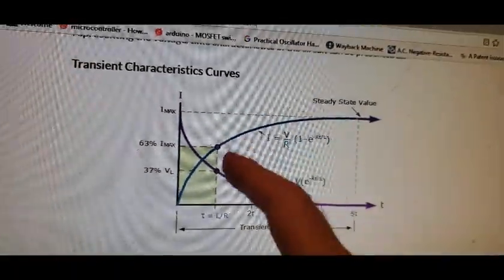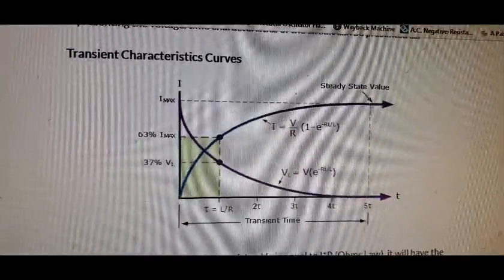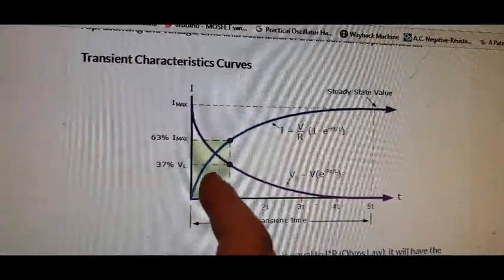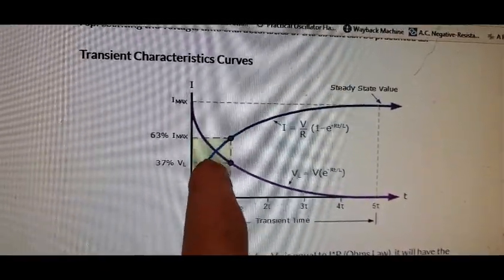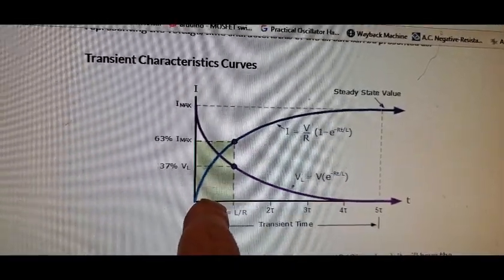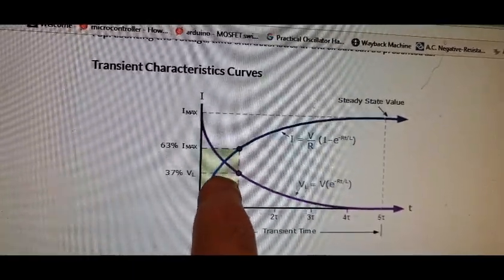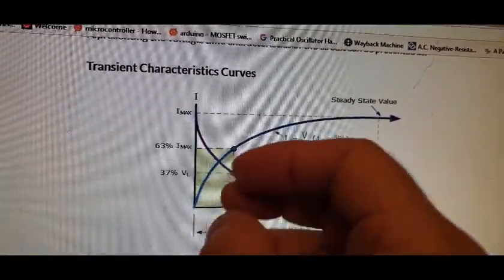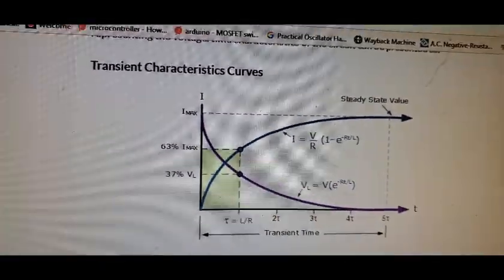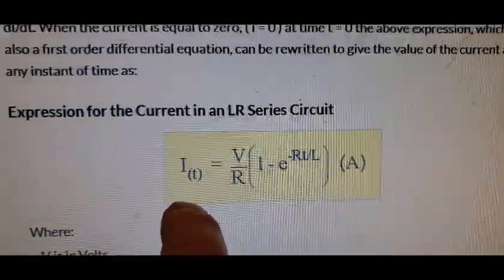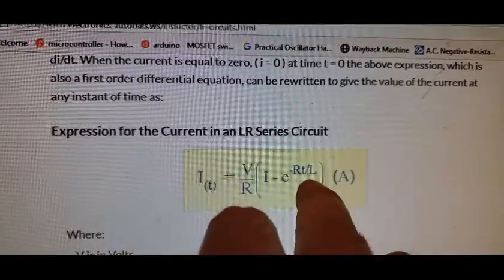But I think I've covered the whole thing now, but it was entitled Instantaneous Amp Flow or something like that. And what I did is I actually went through this, and you see you would need calculus to figure out the area under the curve for how much charge you exactly use to establish any given field strength. And what I did is I just sort of cheated with the spreadsheet and approximated. I mean, here's the expression for instantaneous amp flow in an inductor.